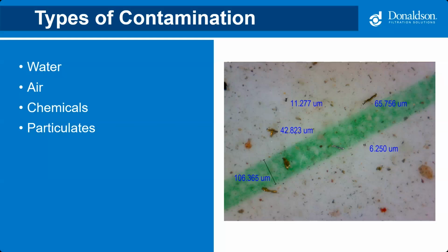And then particulates, the best way I think about it is at a macro scale, if you added sand to something, you're just allowing that sand to sit there and wear back and forth. And that grinding back and forth of sand within that fluid between machine surfaces is going to create more little particles that end up coming out, and you start to accelerate really fast when you have particulates within that fluid. You accelerate the wear of those machine surfaces and can cause issues with that.